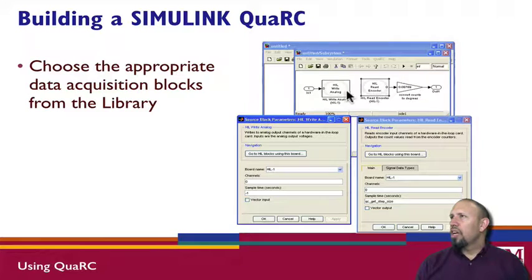Okay, and so I have created a subsystem such that basically I can use this kind of block, subsystem block, to create like a motor block. So the motor block, you would write an analog voltage out to the motor. You would then read the encoder, and then this would convert, if you have an encoder with 500 pulses per revolution, this will convert those 500 pulses per revolution into degrees. Okay, so it converts the encoder signal into degrees. And so the input is voltage, output is degrees.